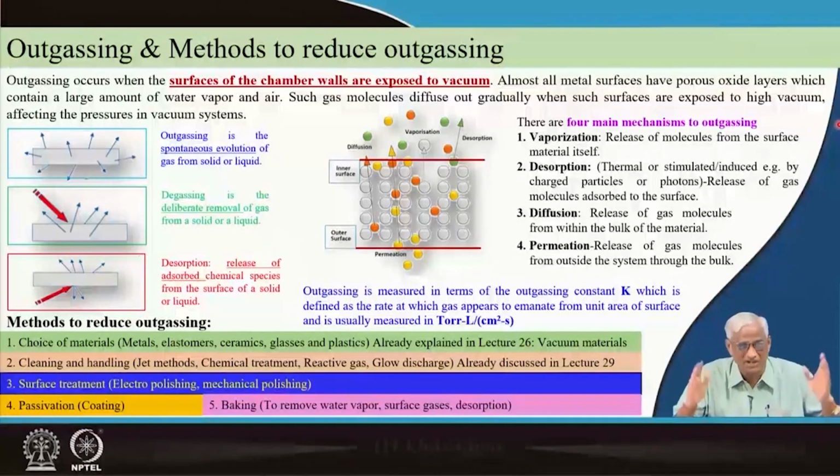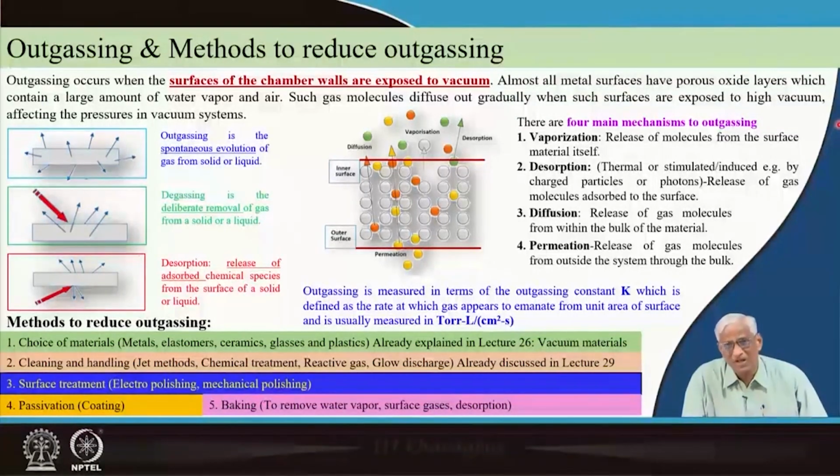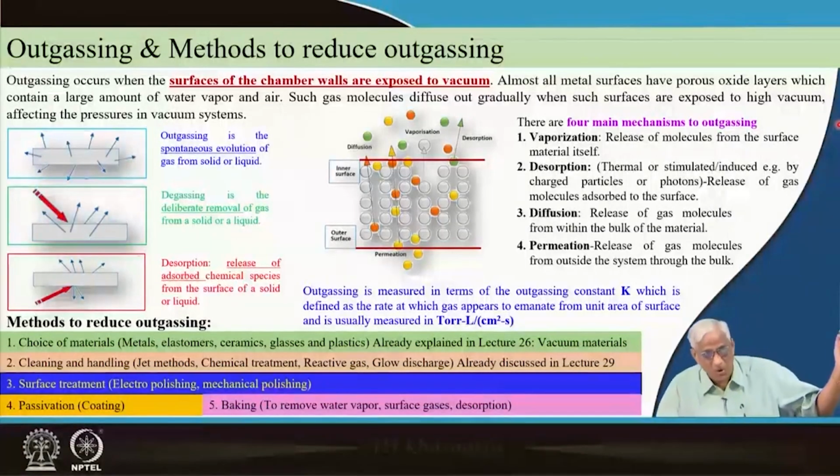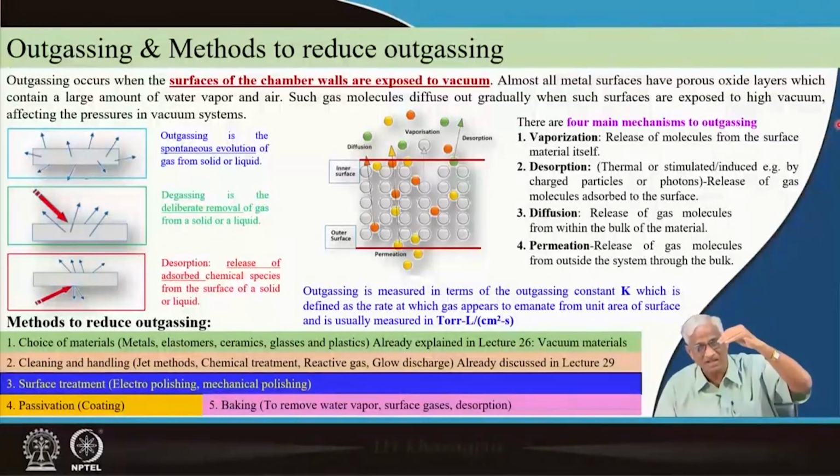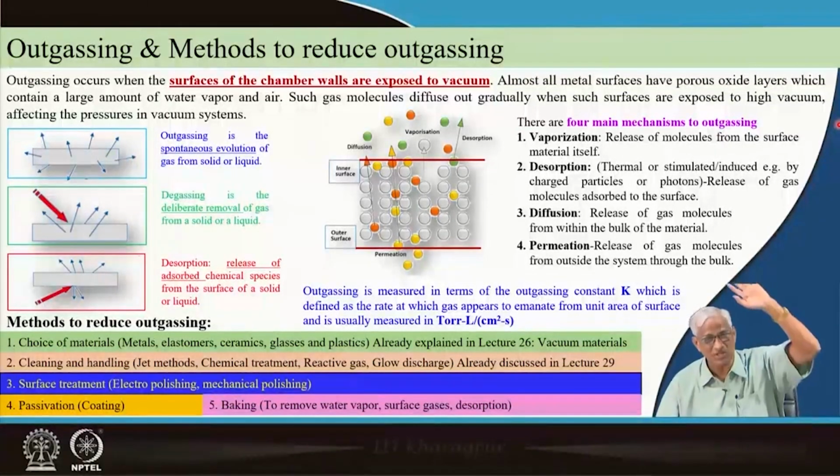But normally food grade high quality stainless steel chambers or pharmaceutical stainless steel chambers with proper welding will work better. But for UHV, even small degassing is not spared, because instead of 10^-10 torr, you will get 10^-7 torr. You should be very careful. What are these outgassings? Material can come from outside, diffuse through the thickness, and then finally come to the surface, and then with some activation it will be desorbed.